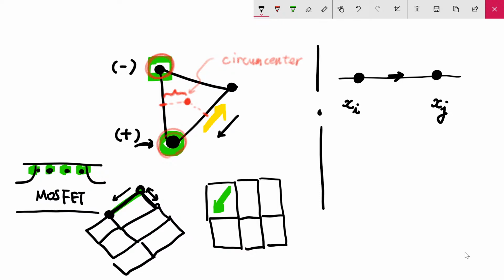But even in this case, if we go very close to the drain end of our channel, then as you may remember, there is a current spreading effect. Here, if we go to the saturation region, then there is no inversion charge. So the current electrons existing here should move in that way.